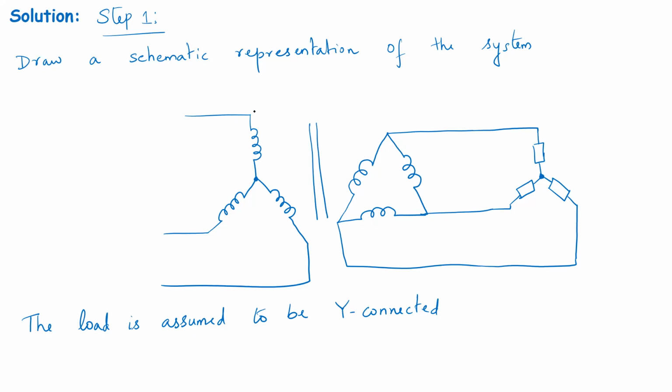So there is a three-phase transformer which has 220 kV on the high voltage side and 22 kV on the low voltage side. And please note, these are line-to-line voltages. If 220 kV appears on the high voltage side, ideally speaking, the low voltage side should get 22 kV. That is what it means. And this is a 100 MVA transformer. So 100 MVA, 220 kV by 22 kV is the rating of the transformer. And the line-to-line voltage that is appearing across the load terminals is specified to be 22 kV. This is already specified in the problem.